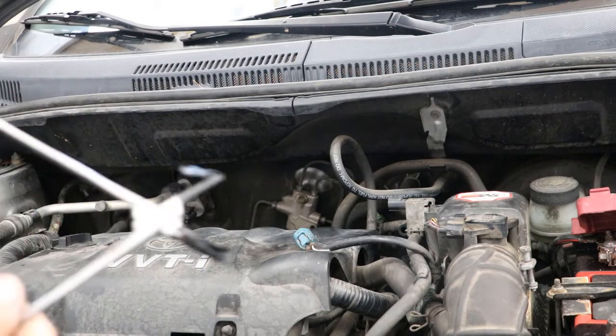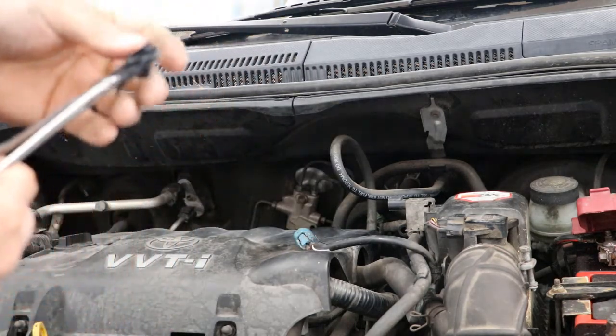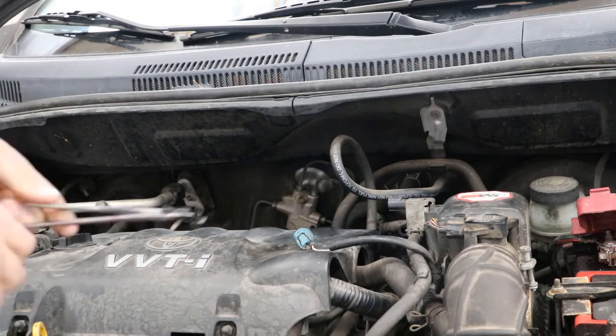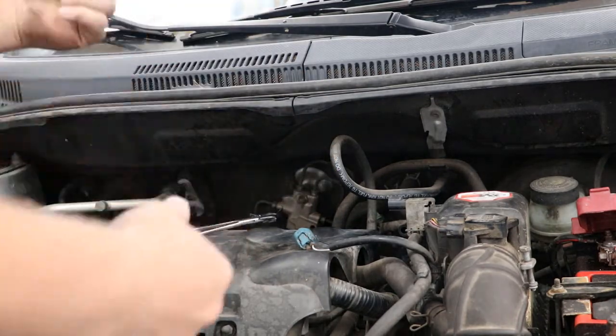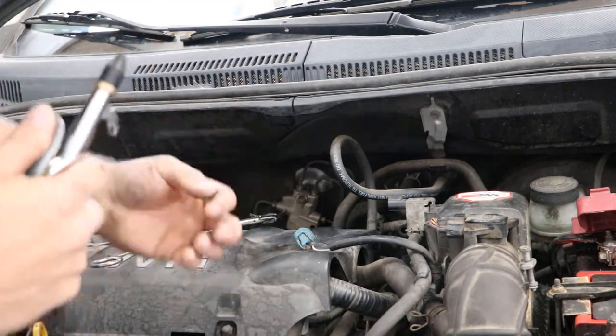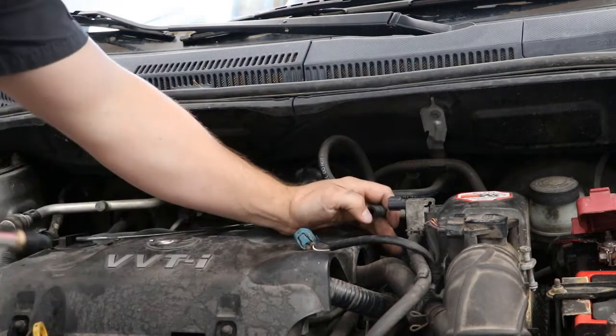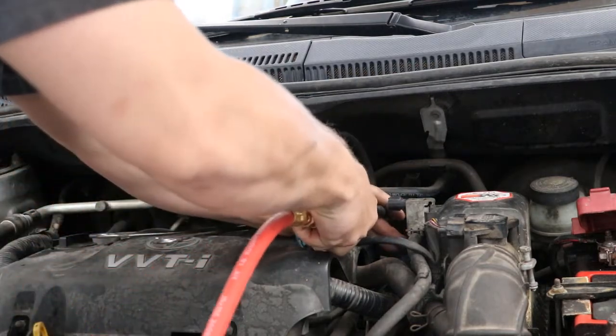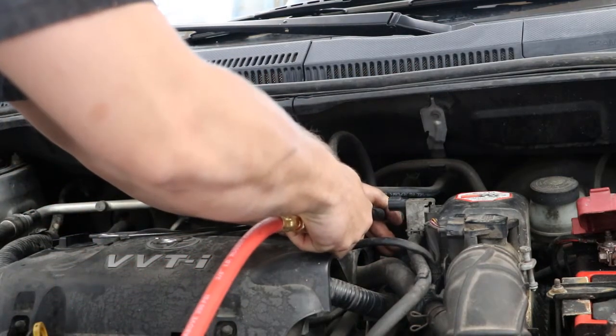So I have a little crimper tool here that I just put black electrical tape on to soften the pinch. I'm going to put pressure on the system and plug it. And once I'm done plugging it, I'm going to crimp it off, and then I'll be able to hold pressure on the system. Unfortunately, I don't have a gauge to inspect that, so I'm going to just put a little bit of pressure here.